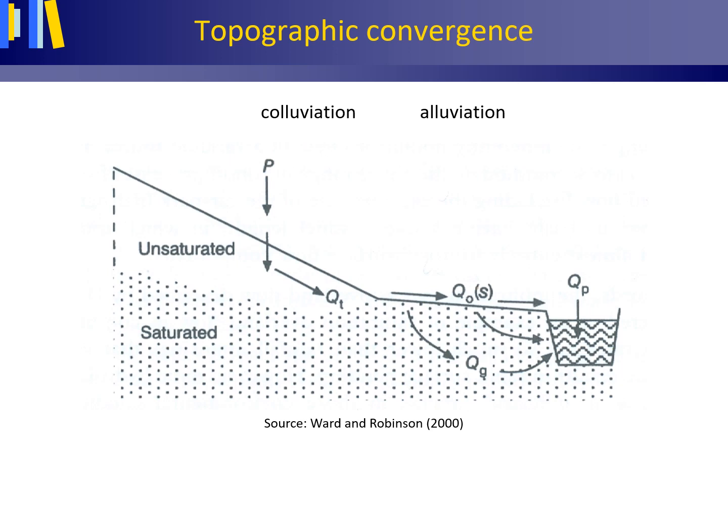These flat areas are called alluvial terraces, and their slope logically is parallel to the former stream's gradient. Thus, processes such as colluviation and alluviation are responsible for having flattened and/or flattening the foot of hill slopes, and thus for topographic convergence that amplifies the effect of a rising water table and may cause through flow to exfiltrate.